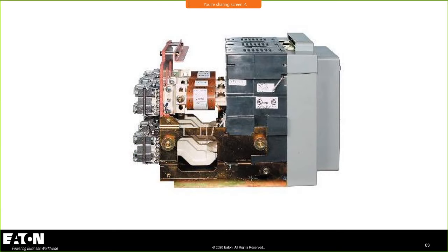And there's just a picture of limiters on a breaker. You say, how do we get 200,000 amps? Well, we put these limiters in series with that breaker, and that limiter will protect the circuit breaker by, again, taking that waveform. Instead of seeing this, you're only going to see this. Instead of seeing that huge waveform, you're just going to see a little blip. You know why? Because these little guys did their job.